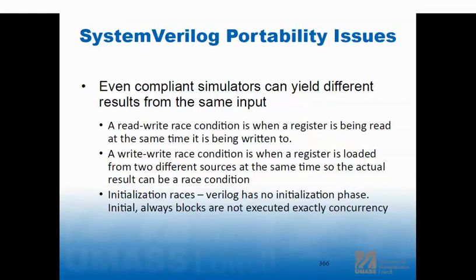Just recognize these things. And as a verification engineer, hammer on those things, right? Anyone can test a memory. Anyone can put a bunch of random data in the memory. The way to really test a memory is if you have two ports, write different data to the same address on every address, and then read them out. And then do a gate level sim, do the same thing. Right? This is the stuff that might not work the same.